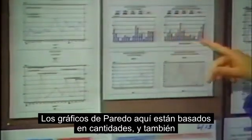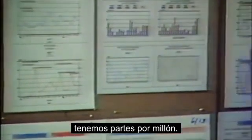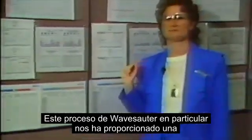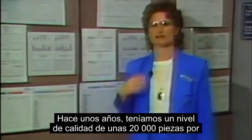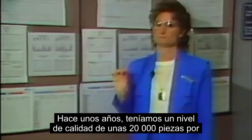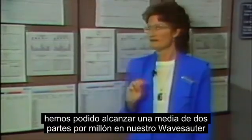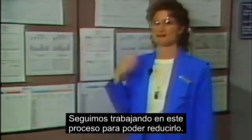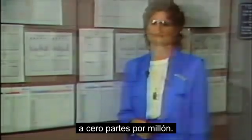The Pareto charts here are quantity based, and then we also have a parts per million level of X-bar chart. This wave solder process in particular has provided us with a real success story with statistical quality control. A few years ago, we had a quality level about 20,000 parts per million in this process. And through using statistical quality control methods, we've been able to achieve an average of 2 parts per million on our wave solder process. But we're not satisfied with that. We continue to work on this process so that we can get it down to 0 parts per million.